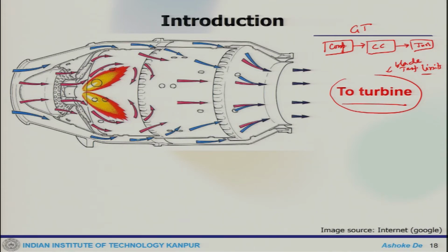So, for a GT unit, all these designs come from the downstream component, the turbine. The turbine blade material dictates the possible maximum temperature, the T max, and this temperature will be maintained through the combustor. This dictates what the hot product entering there could be.